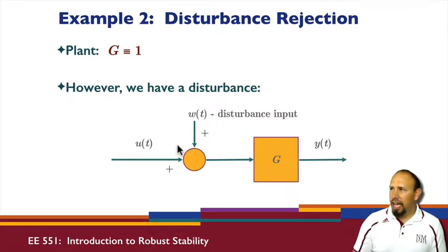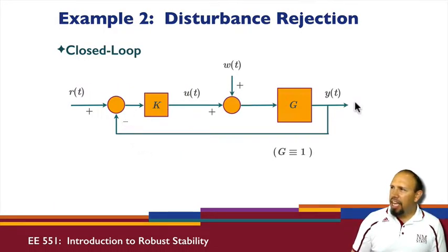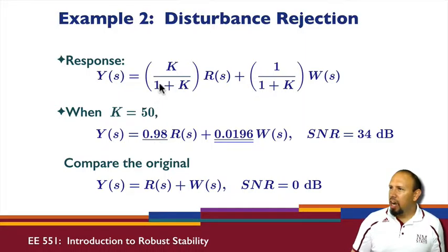So using feedback was one of the early applications for uncertainty like that. Here we have an uncertainty entering in the same place as our control signal. So they basically have the same authority as one another. That is, this one can control my system just as much as this one. By applying a closed loop and this gain, we have upped the authority of our system. And so by upping that authority, our transfer function now is given by this instead of this.